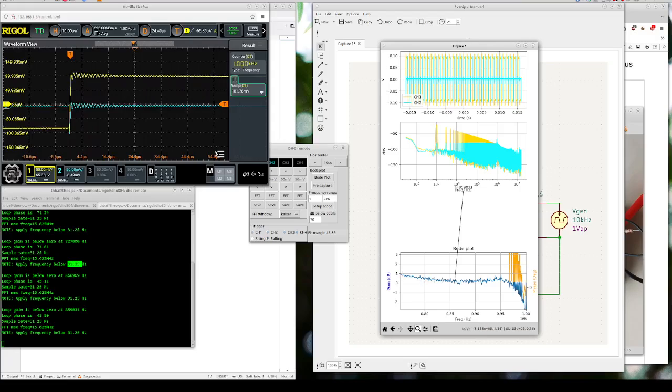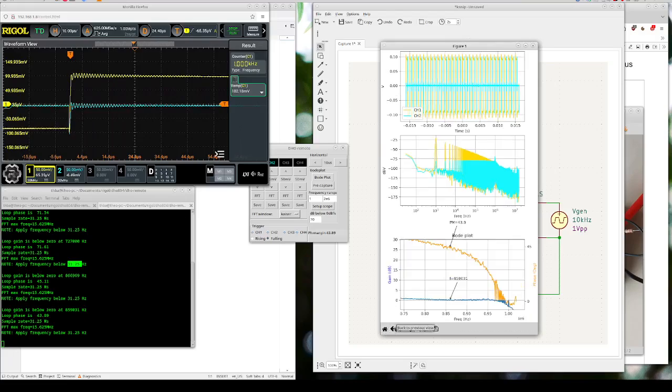But if you take the average of this curve, I think it is more fair to say that the crossing is over here. This is barely above 0, and that is shown by the lots of ringing. So I expect a phase margin of a few degrees. Instead of here, I expect the proper reading should be here.